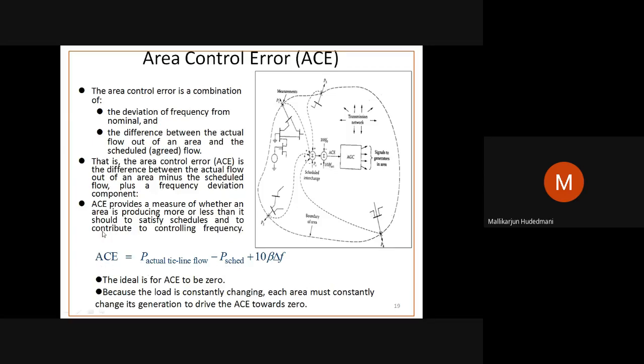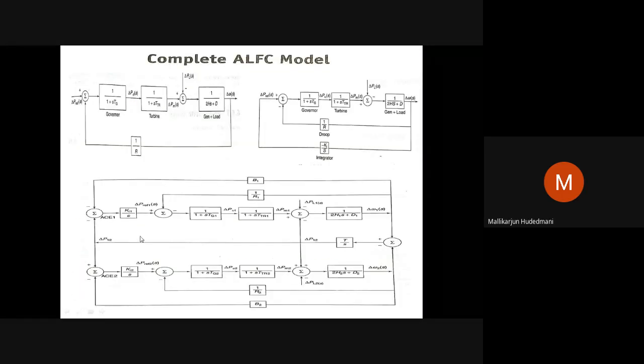So this ACE parameter is visualized in this diagram. ACE defines the need for power here. Why does frequency deviation occur here? If you connect mathematically, frequency deviation occurs because of the mismatch of megawatt. Why has the mismatch of megawatt occurred? The primary controller did not manage it, even after working to the fullest controlling point, to bring it to 0.